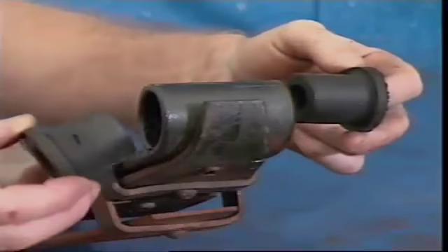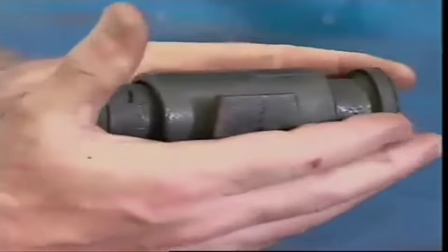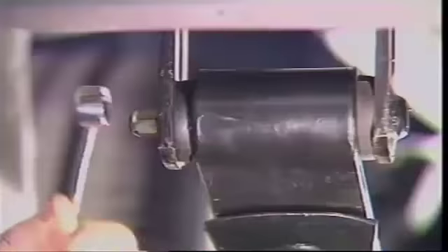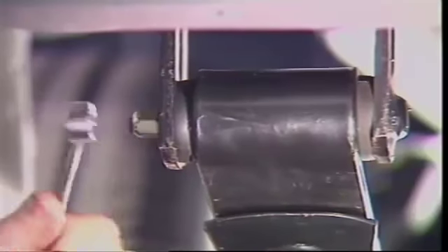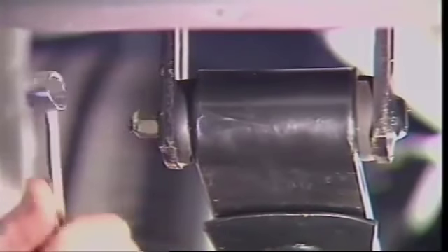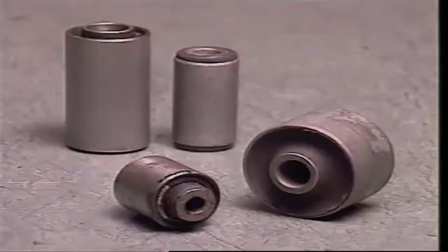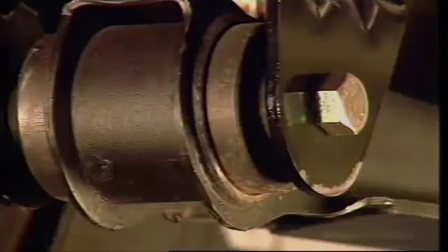Spring shackle bushes can be moulded to form two halves to fit into each side of the spring eye on the swinging shackle. With the spring loaded and the shackle plates tightened, the rubber is compressed in the eye and at the face of the plates. As the spring deflects, the rubber shears without tearing. Metallastic or rubber bonded bushes are normally used for the front eye of the spring at the fixed shackle point, and also in control arm applications.